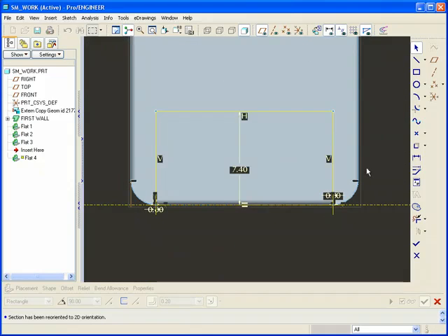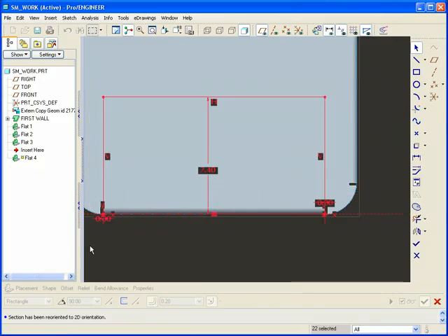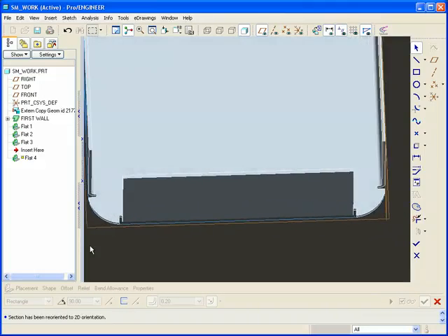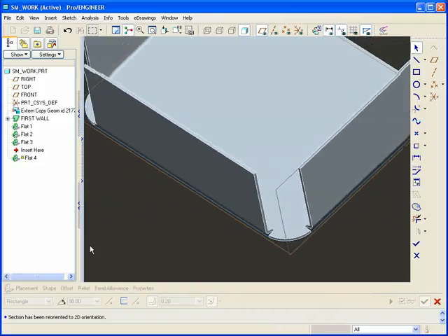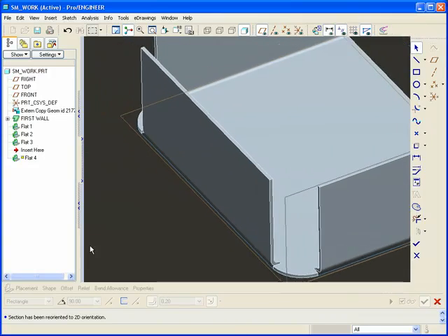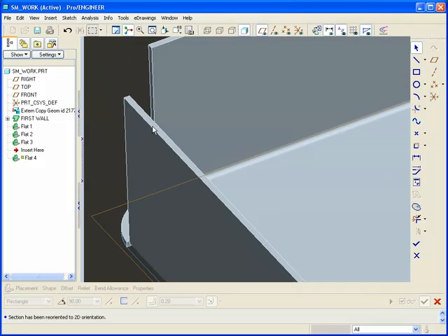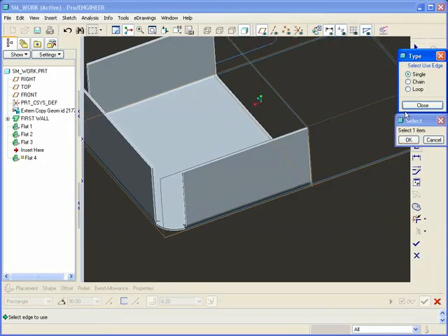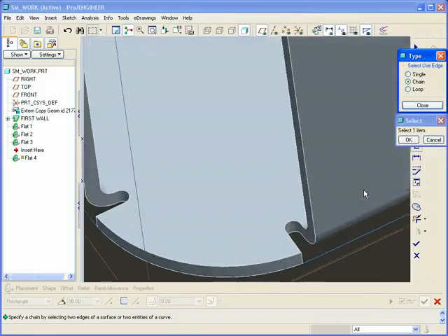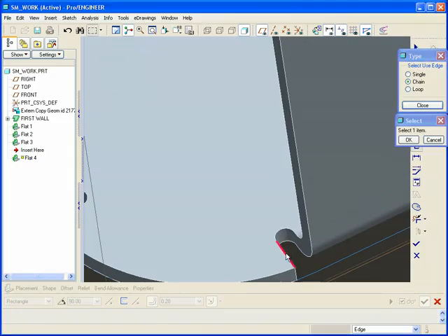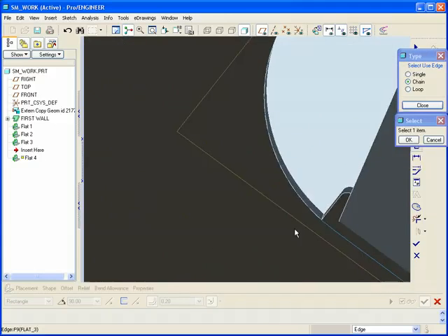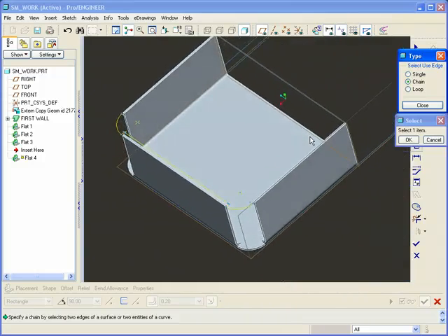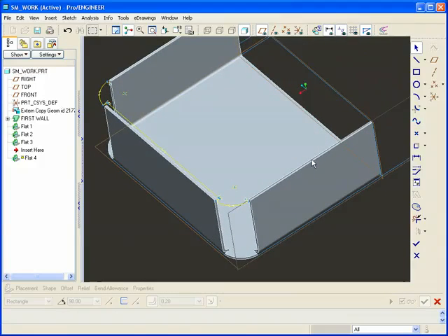and in this case I'm just going to box everything and delete it all, and take advantage of the fact that we've already got quite a bit of geometry on the bottom. Now, you know, when we create a wall and we pick an edge to attach to, the edges of the sketch must connect to those edges, that vertex. So watch this. I'm going to use edge. In this case, I'll use a chain that goes from, say, here all the way over to there. That's the edge chain that I want. Okay, so that gives us a very quick way to pick up all those edges.